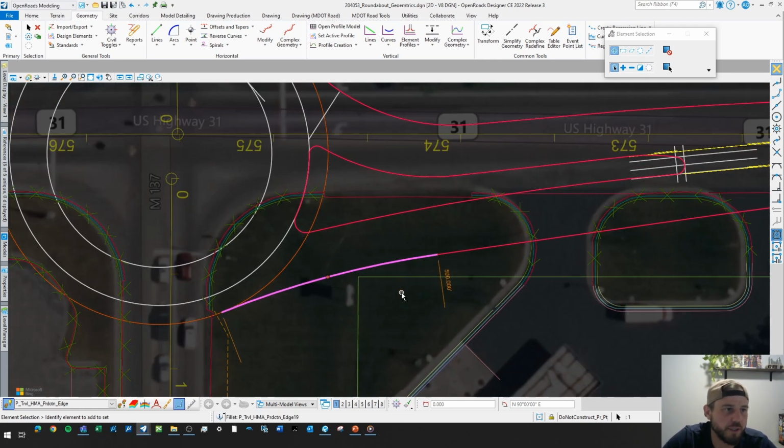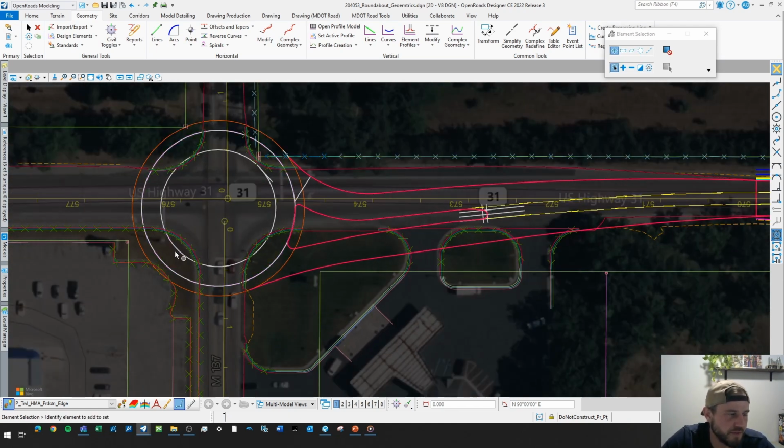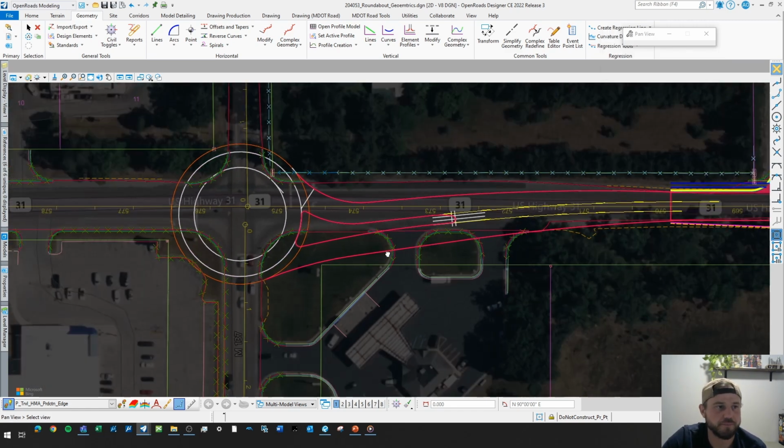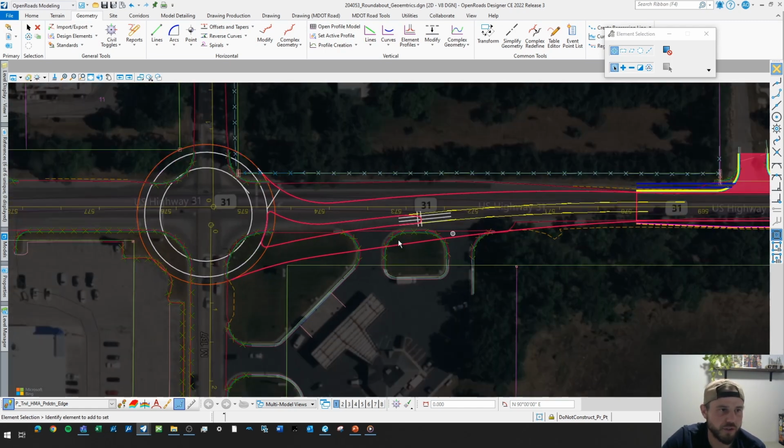I'm not really too worried about that. The idea being that this movement here is going to slow traffic down. They're going to be at 20 miles an hour coming around this curve. The point of interest being back here, they'll only be able to accelerate so fast from 20 miles an hour up to a speed that I think will still be, as long as this V3 speed is within 15 miles an hour of this V2 speed, then you're within the parameters on it. So I think we'll be able to achieve that even with this straight kind of shot.